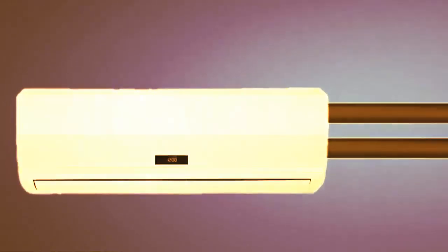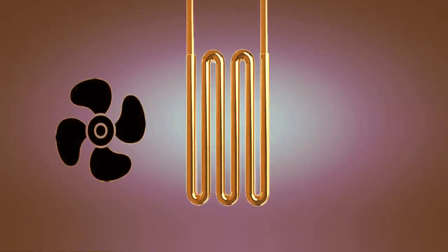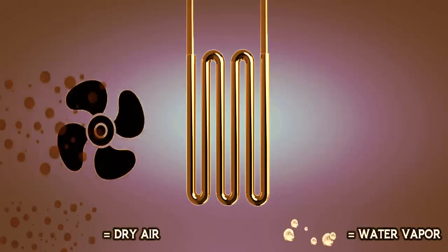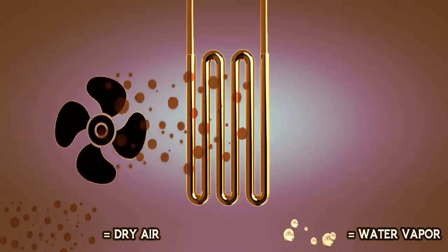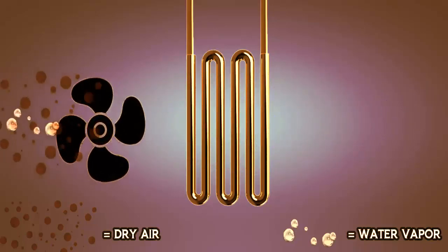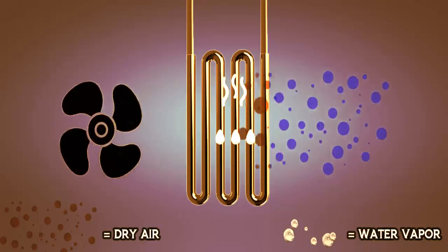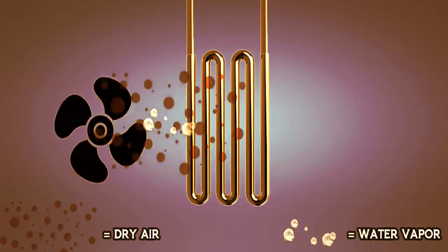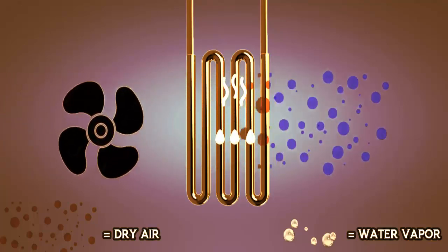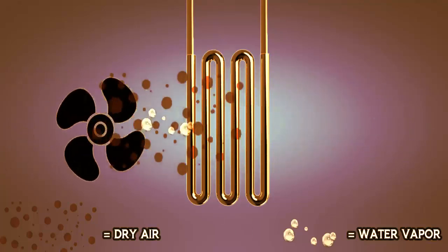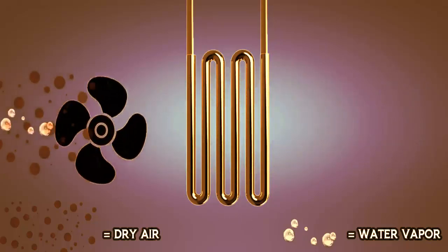Normally all AC units reduce humidity levels. The entire process of reducing humidity takes place in the evaporator coil. Refrigerant travels at a very low temperature in the evaporator coil. This makes the evaporator coil very cold. All the air in the room travels through the evaporator coil using a blower fan. When the air travels like this, the water vapor in the dry air also travels through the evaporator coil. When dry air travels through the evaporator coil, its temperature decreases and we get cool air.